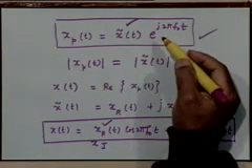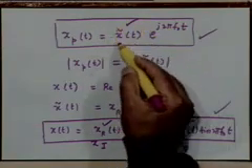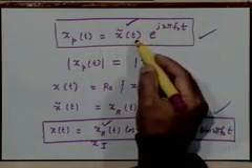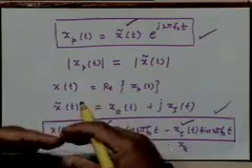In fact, that is the case. You could exclusively deal with x tilde(t) and get back to the result of processing or analysis by just multiplying whatever you have got with e to the power j2 pi f naught t. That's the power of this. Let me illustrate this by taking a very specific example. Have you understood what I am trying to tell you? I will try to make it more clear by considering